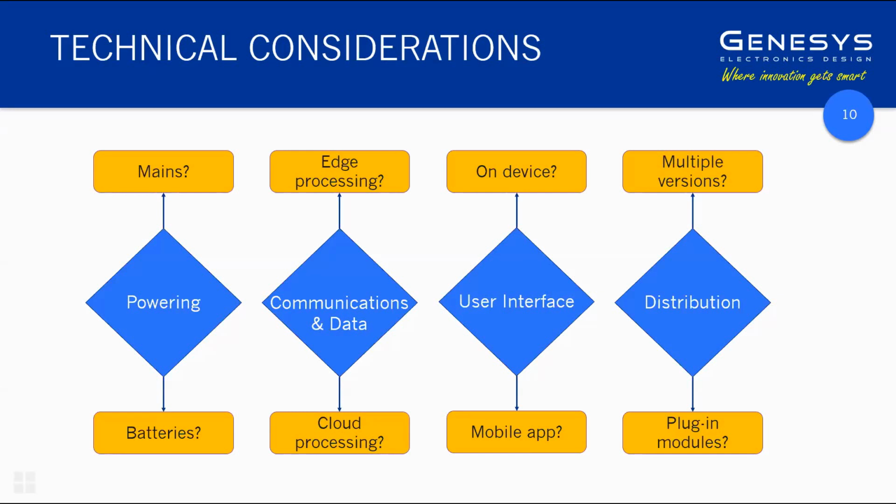Just to comment on that, there's a standard IEC 60601-1, which is covering safety aspects of medical devices, including function and electrical safety. If you go for an enclosed battery pack solution with no external electrical contacts, about half of that standard becomes not applicable. So you can dramatically reduce the regulatory compliance burden for electrical safety by avoiding having mains connected to the device whilst it's being used on a patient.